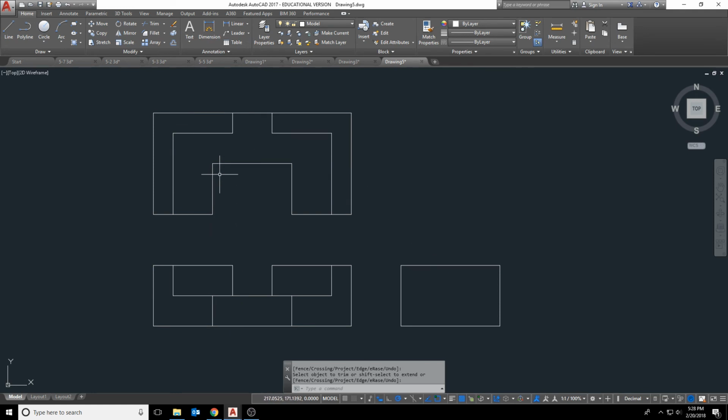Based on what we analyzed in the 3D view, there's no hidden lines in my top view or my front view, so the only one I have to worry about the hidden lines for is the right side. So I'm going to come up here and go to my hidden line layer, and I'm going to start the line command. Now I know that I have a hidden line that goes all the way across here because I've got this surface and this surface here to make up that goes all the way across.